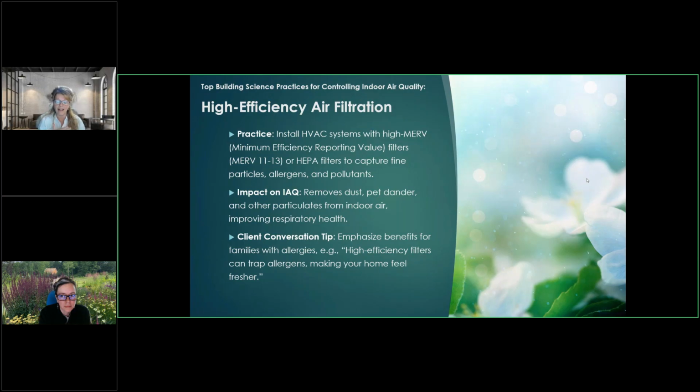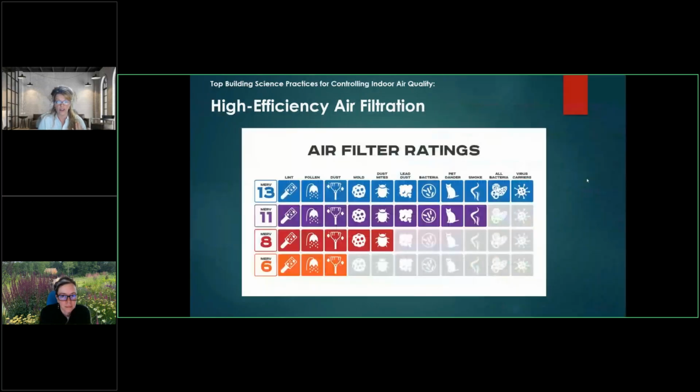But these are decisions that have to be made early on in the design of the HVAC system, because they are going to add static pressure to that system. So it's hard to do as an afterthought. Having that conversation up front is very important.